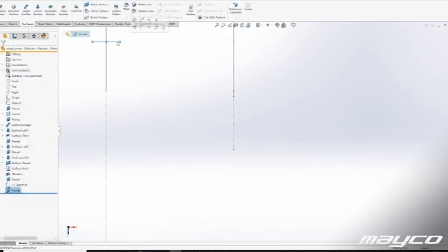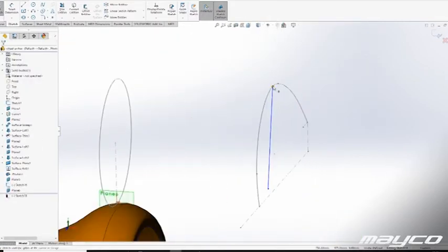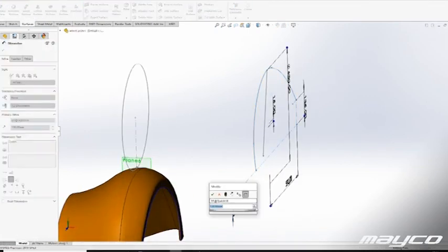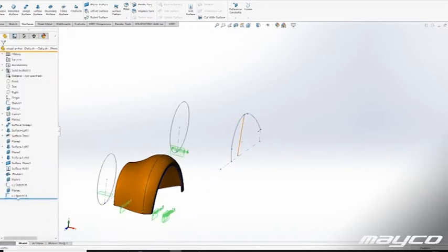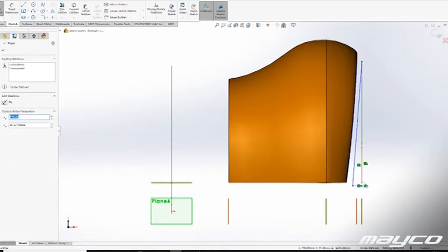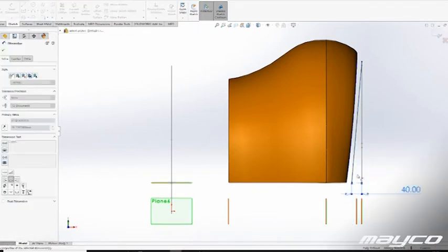One of the big things that will go wrong a lot is that you get these weird angles and you cannot find your way out of it except for a triangle. A triangle you cannot do in SolidWorks with surfaces. It doesn't understand triangles.